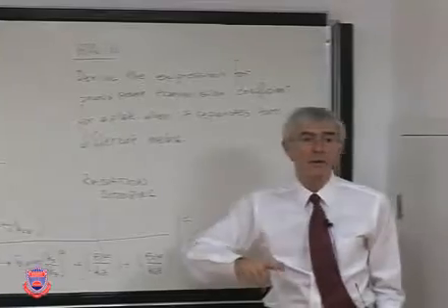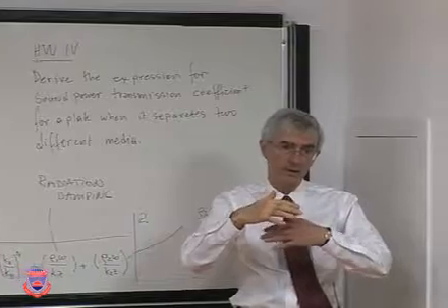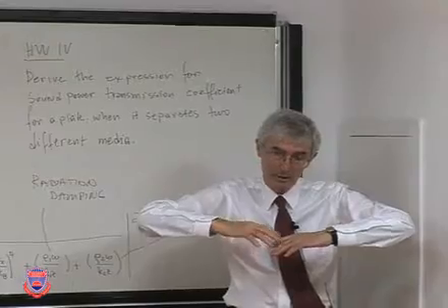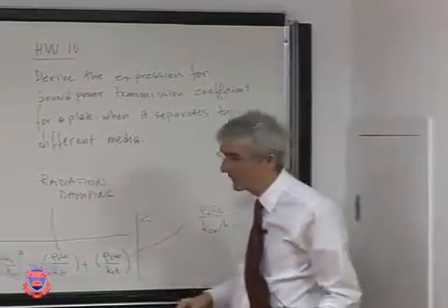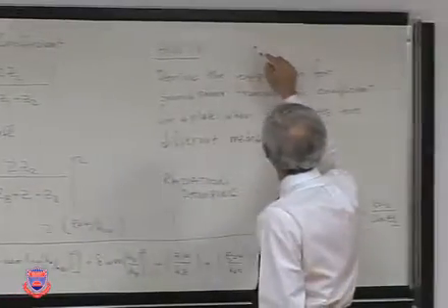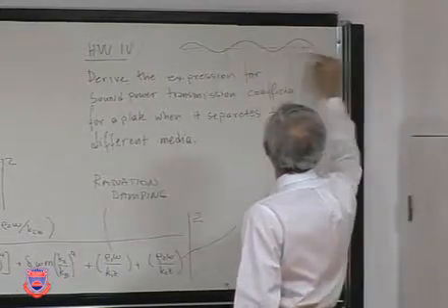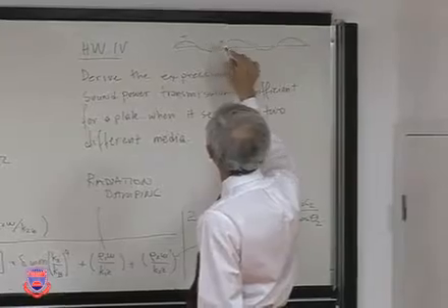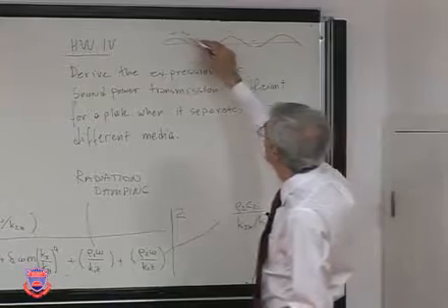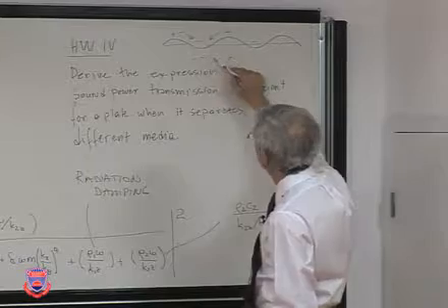How does it react? If these numbers were imaginary, then they again would be part of the reactive field. That means energy doesn't go away. It's an exchange of energy with the fluid. It vibrates, it pushes from here, but the other side pushes it back. When you think about a plate vibrating like this, in one cycle, it pushes the fluid up, down, as it moves up and down. So the fluid really just goes here. In the next cycle, it goes back.